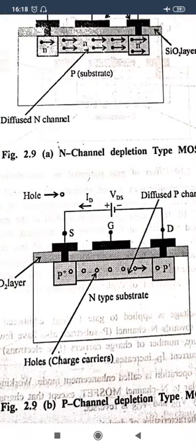Here we'll explain the P channel. In case of P channel, the majority carriers are the holes, so heavily doped P-type regions are present there. In this case, we connect the drain terminal towards the negative terminal and the source is connected to ground. Depending on the controlling voltage, called the gate voltage, whether positive or negative, the current flowing between the drain and source terminals depends on this particular gate voltage.